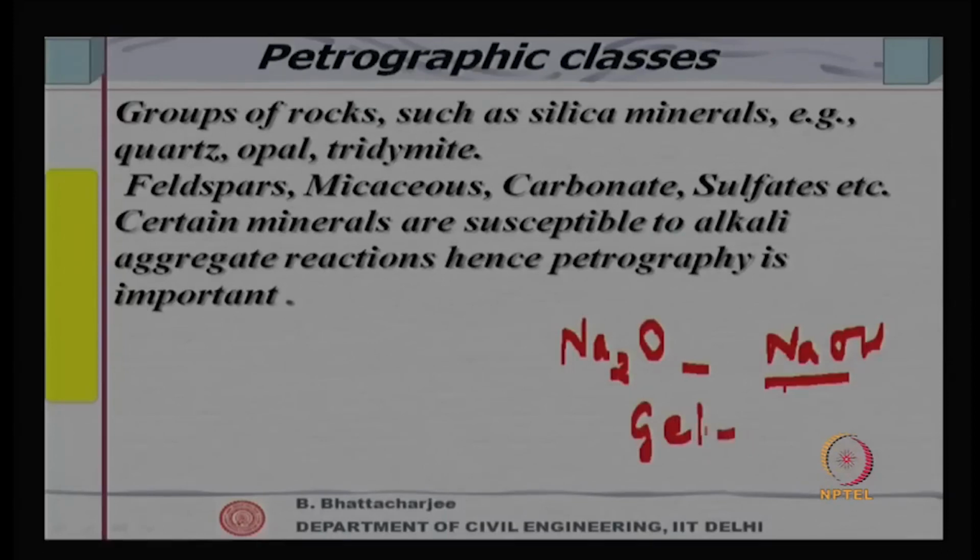This gel adsorbs water and increases in volume. And this expansion in hardened concrete can cause cracking. We will look into this issue of alkali aggregate reaction in detail when we talk of durability of concrete. So, certain aggregates are prone to such durability problem and cause deterioration of concrete structure.